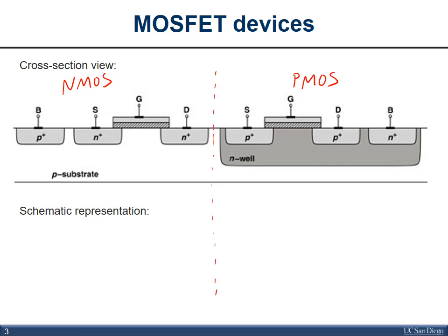The NMOS is technically a 4-terminal device. We typically draw it as 3 terminals, the gate, drain, source, but we do have that bulk terminal that we may end up using fairly significantly in this class. If we neglect to draw the bulk terminal, we typically just draw the transistor like this. Sometimes people will also draw the transistor like this, although it's not very fashionable these days.